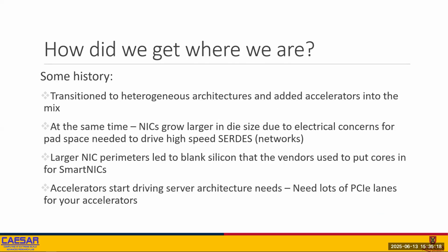So let's talk a little bit about how we got where we were with SmartNICs in the first place, right? SmartNICs were not a product developed in the presence of a problem. They were a problem on the product development side that ended up in a solution that now we have to figure out how to use, right? So the problem was when we started growing NICs and NIC architectures, we started doing some things with regards to the pad space that we needed, which led to the definition of how you build the actual dies for these NICs. And in that, you ended up with a whole bunch of blank silicon that you actually weren't using in the NIC logic. And so everybody was like, hey, can we fill these places in? And the answer is yes. But then people said, okay, now that we've added these capabilities of SmartNICs, what do we do with them, right?